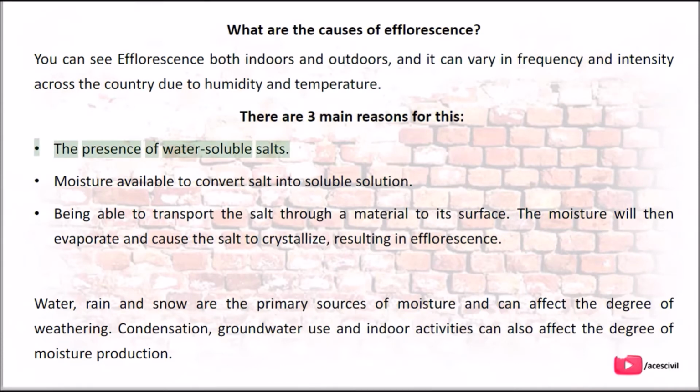The presence of water-soluble salts. Moisture available to convert salt into a soluble solution. Being able to transport the salt through a material to its surface. The moisture will then evaporate and cause the salt to crystallize, resulting in efflorescence.